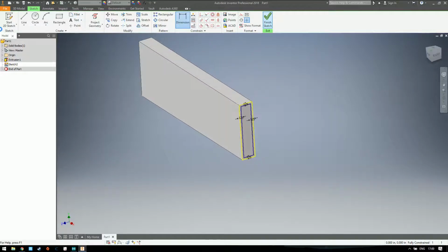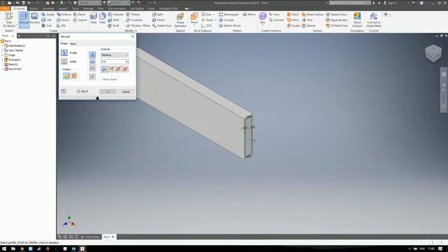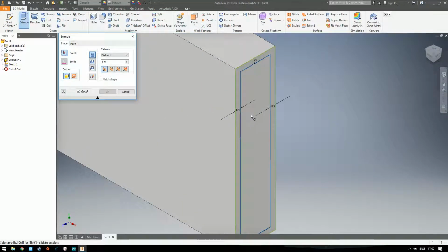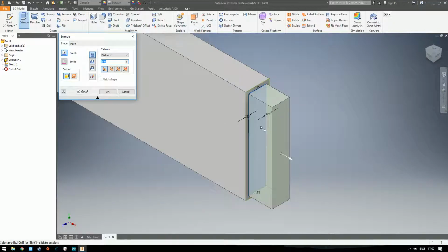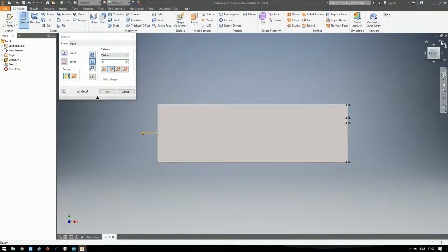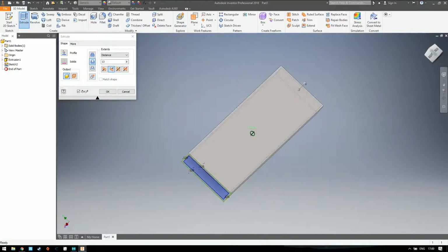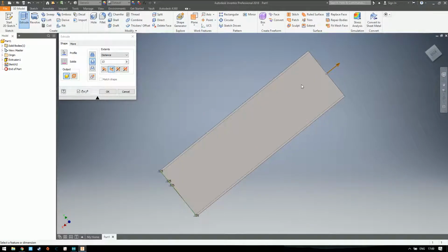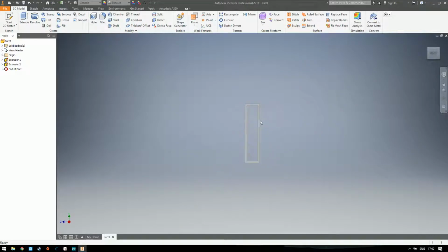So finish sketch. Click extrude, click on only the closed side. It lights up a little bit. Probably you guys cannot see it, but you have to click it. Remember what I said, if you want to drill inside something, click direction 2 and all the way down. You will see a red rectangle inside the object you already drew. Click OK. And you go to the side. You can see it's perfect.